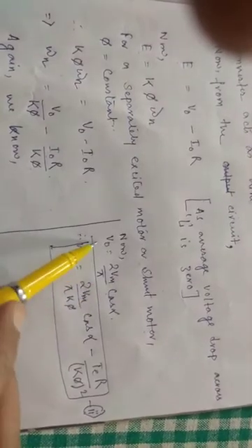So torque is equal to... see here, Ia is equal to I0, so I0 is equal to Te by K phi. If I0 is equal to Te by K phi, then omega n can be written as V0 by K phi minus, in place of I0 we put Te by K phi, so Te into R by K phi square. In that case, V0 we know is 2Vm by pi cos alpha, as we have derived it from the waveforms, and we just put this value in place of V0 here, and we get this equation 2.